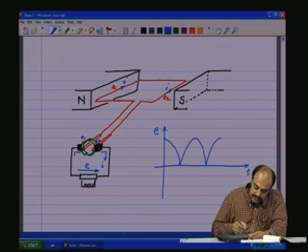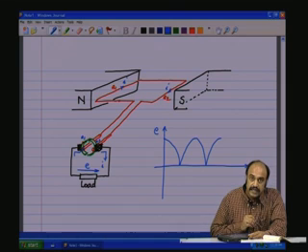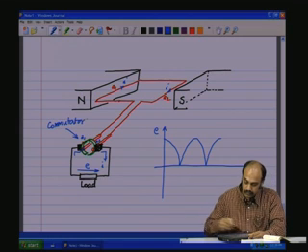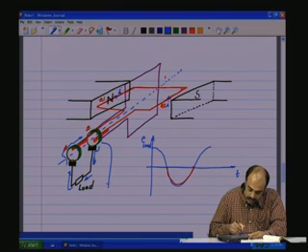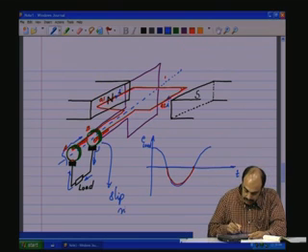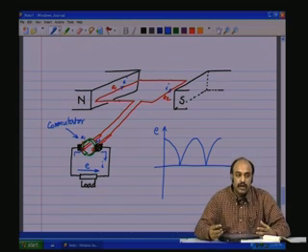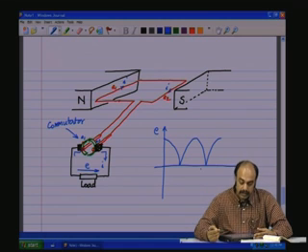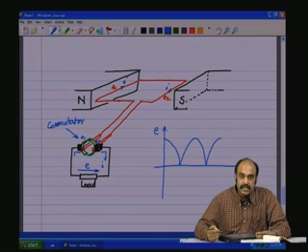So there is a rectification which has come about due to the way in which this ring has been made. This is called the commutator. The way the ring was formed in the AC case is called the slip ring. So the commutator can be used for obtaining a rectified waveform at the output, and thereby we get a unidirectional induced voltage, and therefore that would be a DC output.